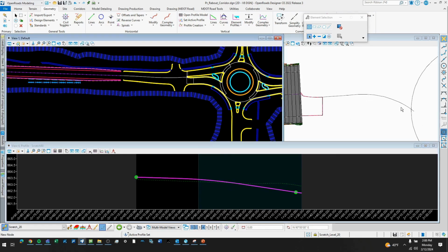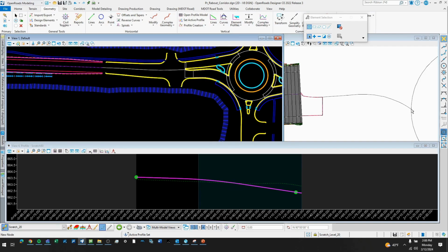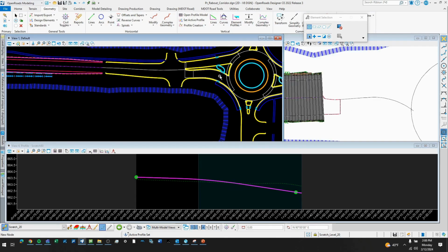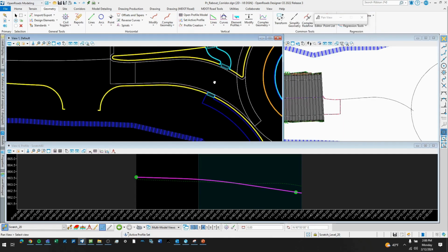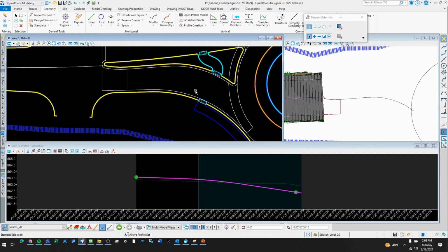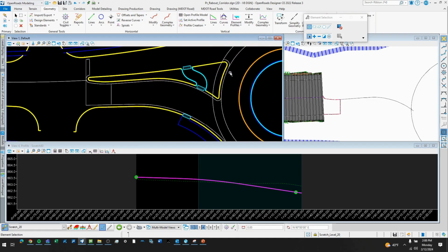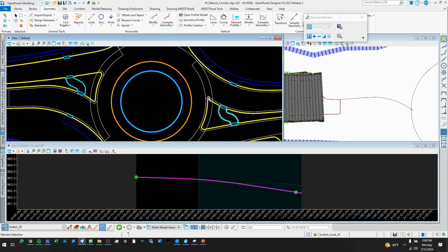So now we got this PGL in there. It's targeted. It's right on that line. We can start building the outside, and this one's going to change a little bit. It's never going to be exactly 2%, obviously, because we're going down this way. So it works here, but in this instance, we're going up in elevation. So this isn't going to be projected exactly 2% off, because this tie-in point is actually higher than this tie-in point.